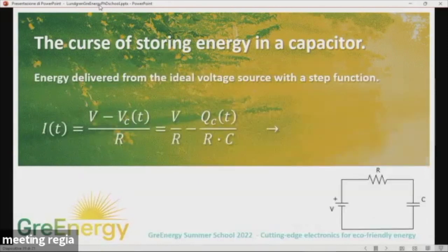So if we say that we take the fastest possible route, that would be to say that we have an immediate switch from 0 voltage to the full voltage on the left-hand side. And then we would have the optimal speed and the speed limitation by the time constant of the RC circuitry.